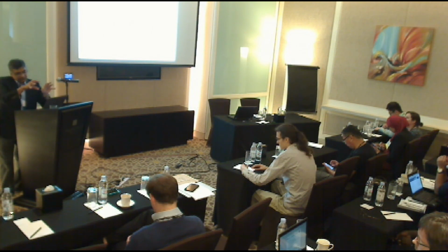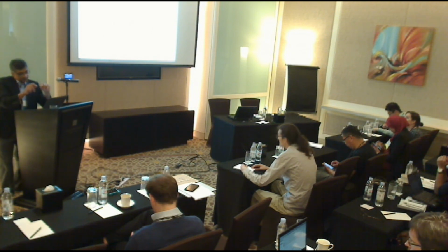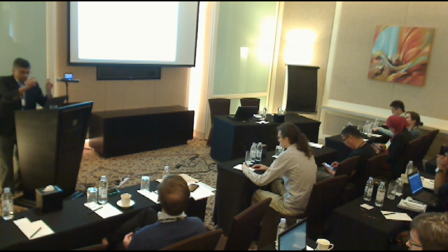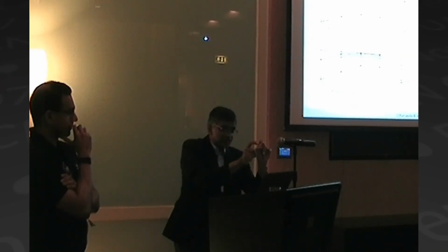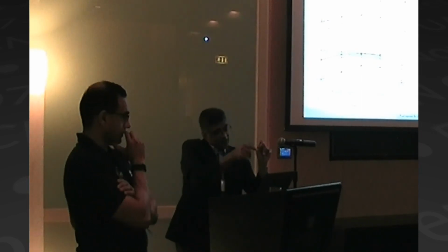Okay, I think we are mixing up two parts. In the network aware nodes, yes, each node has its own view of the network, right? So that is part of it. But if you go back to the structure where you have a set of anchors and the nodes have a consistent view, then all of them have the same map. So we are doing the tracking on those maps. For example, when a target moves, it goes past certain nodes. From that, they know the distance between them in the topology domain. They can estimate the acceleration, deceleration, velocity, and predict where the targets are. So in the case where we are doing target tracking, we are using a consistent view of the map.